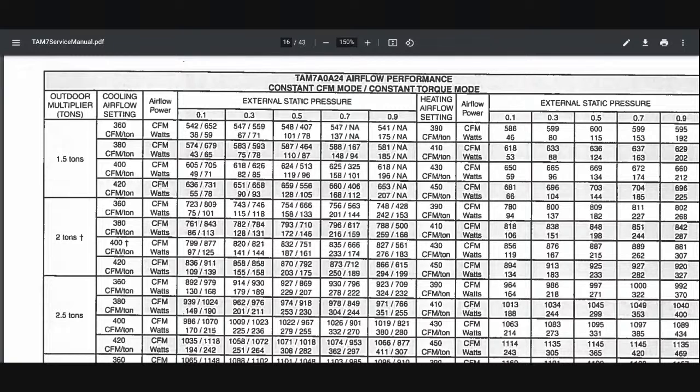Now, that doesn't mean that the ductwork's okay. Maybe the supply side's blown out somewhere and it's dumping a bunch of air. So you have to take these things into the bigger picture. But my point is, it is better to see a lower external static than higher. And if you walk up and you see that your evap saturation and your superheat are already struggling because they're low, and then you take a quick external static, which once you get familiar with it takes minutes to do, it's not a complicated procedure.